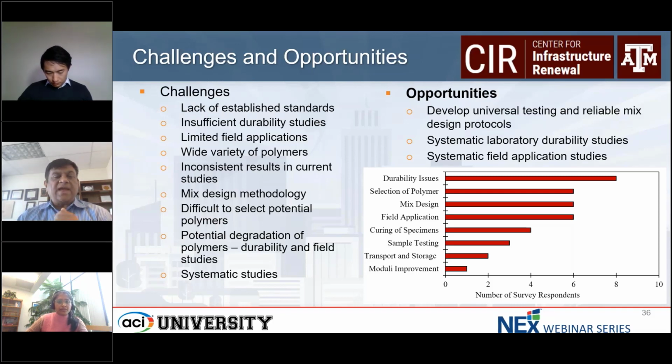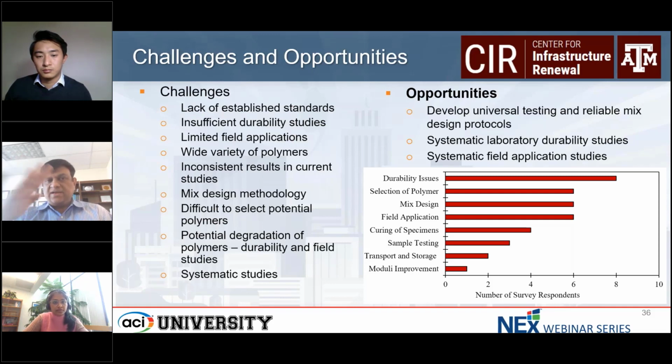Let's say I'm doing a dam embankment, and the embankment has maybe an erosion problem, and I found a certain type of polymer can be a good product, and I can do spraying very quickly because this is at an angle. So I just use some kind of pump at the base of the toe of the dam, and then apply this treatment, and then mix it, and then rapidly I can finish the project. So it depends on the type of project or infrastructure, and also how quickly I have to do the work.